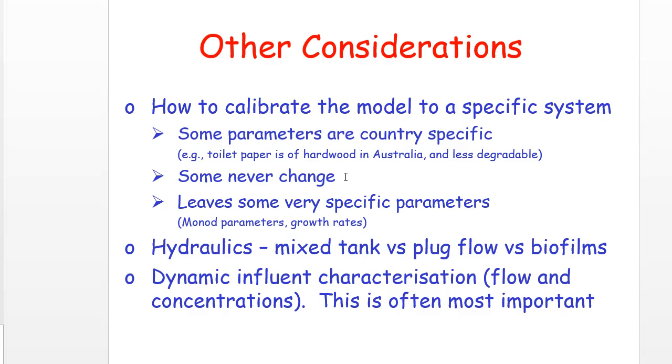So therefore never touch them, such as those that go into the Monod rates, growth rates. On the other hand, hydraulics, of course, can change a lot. But most of the time we work in mixed tanks. Sometimes we do plug flow, sometimes we do aggregates, such as biofilms. But as we move to the right here, the model becomes much more complicated in terms of numerics and everything, but also very useful.